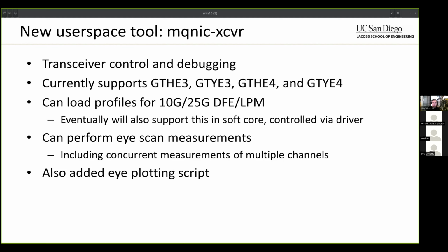I have some TCL scripts that I put together to extract those parameters. It's pretty simple if anybody else is interested in doing that for some reason. The way this is done in the tool is still kind of rudimentary. It doesn't really do a whole lot of checking besides trying to figure out if the PLLs are set up such that you have either a single 10 gig PLL, or QPLL 0 running at 25 gig and QPLL 1 running at 10 gig, and then it'll allow you to load the corresponding profiles.